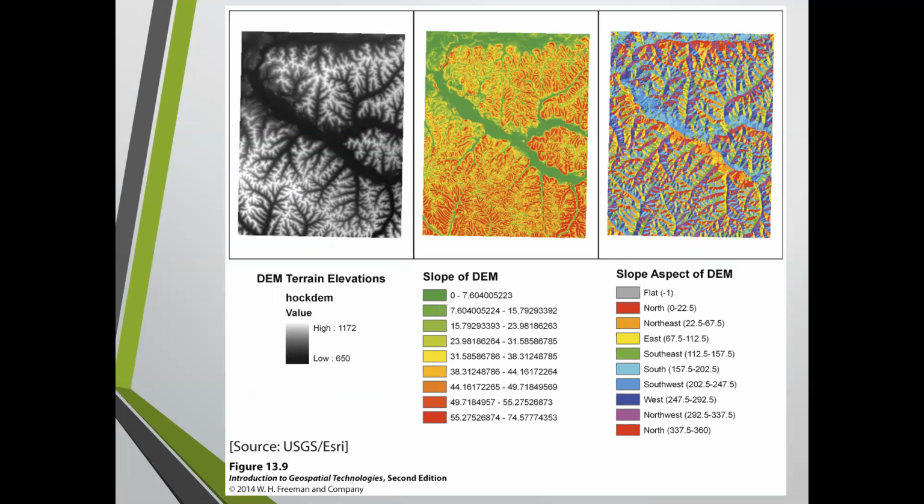You can kind of see those directions of creeks and everything that is developed. And you can kind of see there's many watersheds that are developed there, and then major watersheds that go together. Now the middle is taking this image and calculating it into a slope of different ranges. So what we're looking at is your greens are your lowest slopes, or your flattest slopes. My guess is that's probably in percent grade right there. So that would be from 0 to like 7.6%. And then we can range these into whatever values we want.